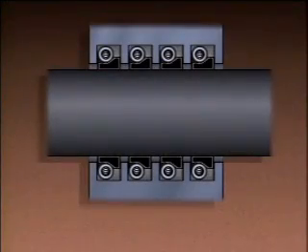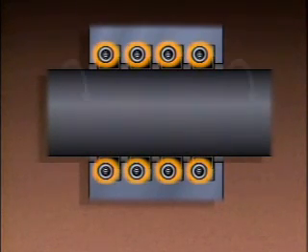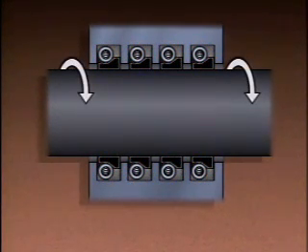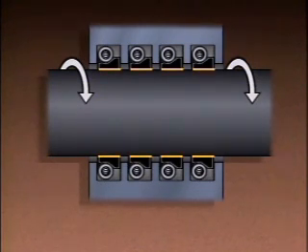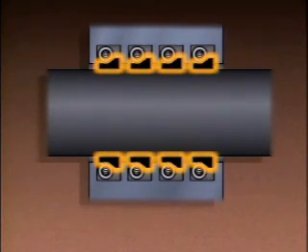This is a cutaway view of a carbon seal. Carbon seals are usually found on low-pressure turbines because they can't withstand very high pressures. A carbon seal consists of one or more carbon rings held in place against the shaft by springs. As the shaft turns, it rubs against the carbon rings, and an effective seal between the shaft and the rings is achieved. Carbon, being softer than metal, creates minimal wear on the turbine shaft. Eventually, the carbon wears down, so the carbon rings must periodically be replaced.